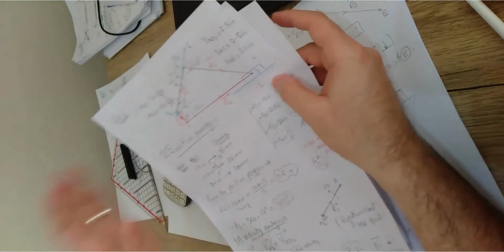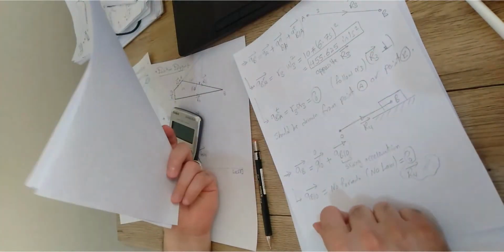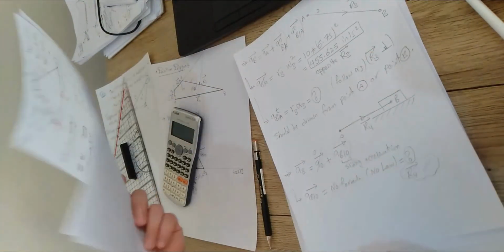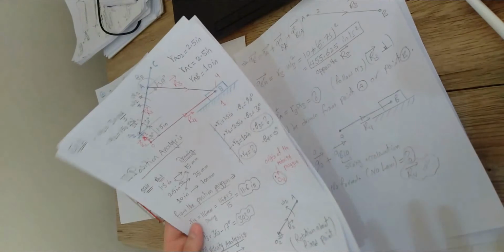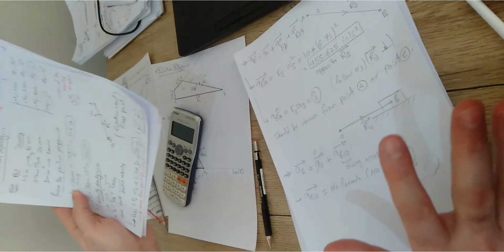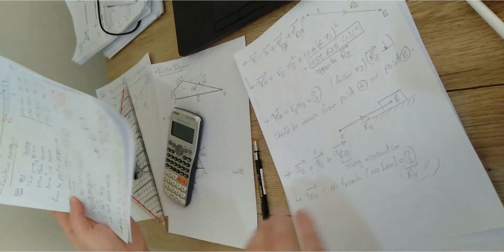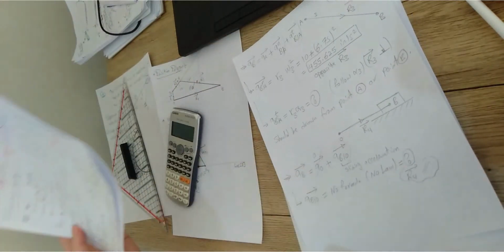So if this slider is constrained to move at a constant velocity, this acceleration component will be 0, and in this case it will be like given, right? But here he didn't give any data or any information regarding the sliding velocity of this slider, whether it is constant or variable. So I'm going to deal with it like a variable, and it means that there should be a value for the acceleration, and we are seeking this value of the sliding acceleration of the slider.